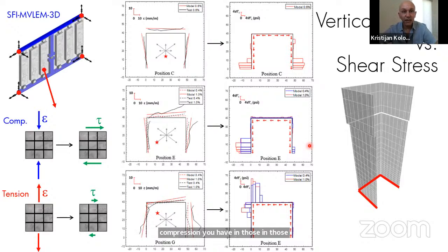If you have a model with shear behavior uncoupled from flexure, like if you're using the Perform 3D shear wall element or even the MVLEM, this shear demand will be averaged out throughout the cross section, and you would maybe underestimate or overestimate the amount of shear force that goes into the web or a flange of a wall, especially when you have multi-directional loading. So again, these results really demonstrate the axial-shear coupling at the fiber level of this element.